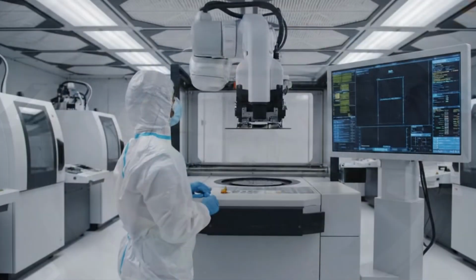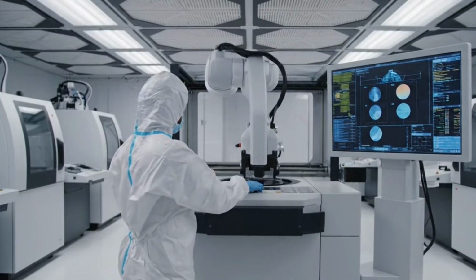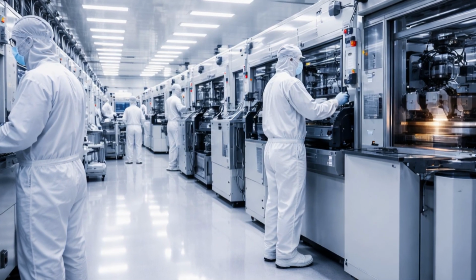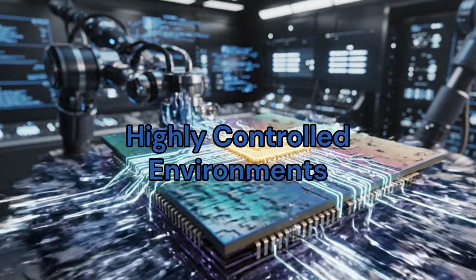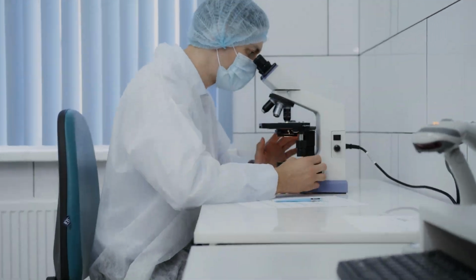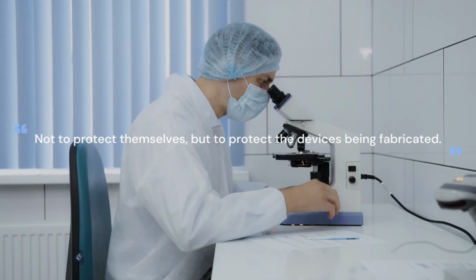All of this takes place inside clean rooms, which are absolutely critical to fabrication. Even a single dust particle can destroy multiple devices on a wafer. That is why fabrication is performed in highly controlled environments where air purity, temperature, and humidity are carefully regulated. Engineers wear full clean room suits, not to protect themselves but to protect the devices being fabricated.